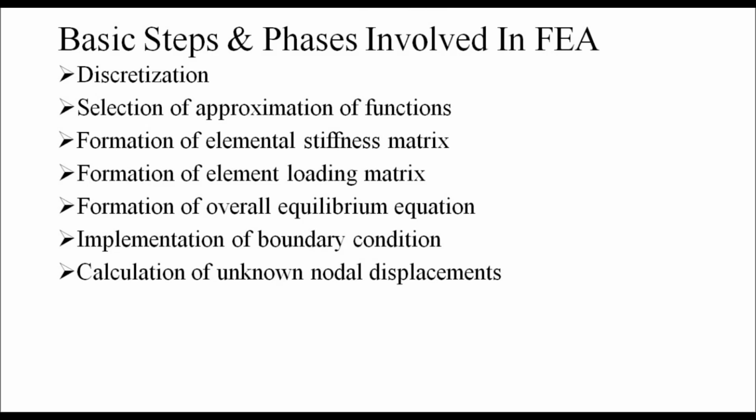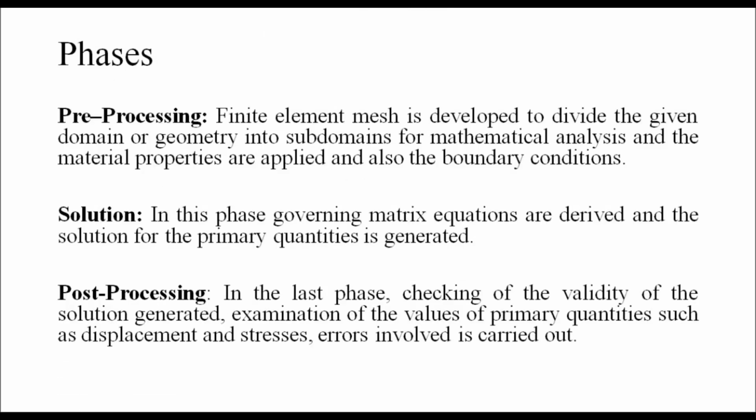And these are the phases involved in finite element analysis: pre-processing, solution and post-processing. In the pre-processing stage, a finite element mesh is developed to divide the given domain or geometry into subdomains for mathematical analysis, and the material properties are applied and also the boundary conditions.